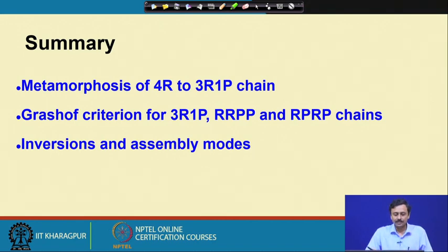So, let me summarize. We began with the metamorphosis of a 4R to a 3R1P chain, then we extended the Grashof criterion for the 4R chain to the other chains, and we have looked at the inversions and assembly modes of these various chains. With that, I will close the lecture now.